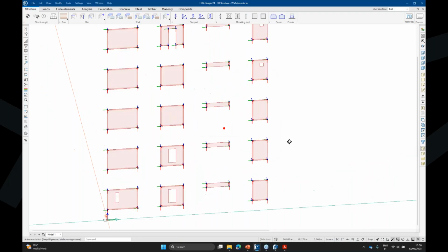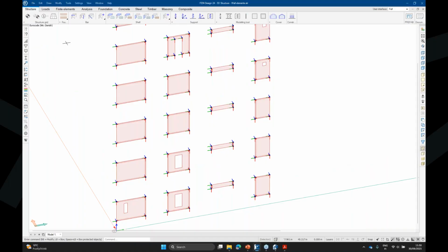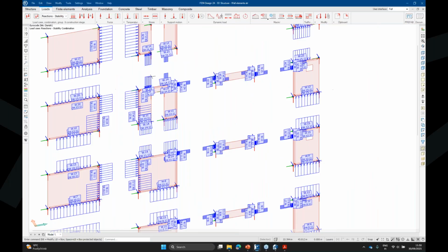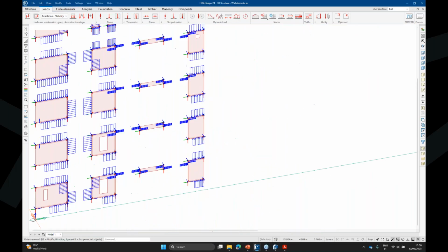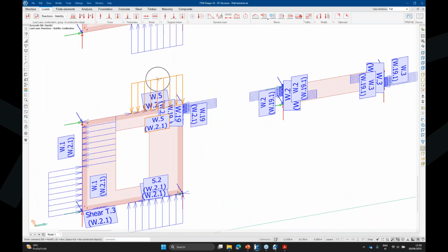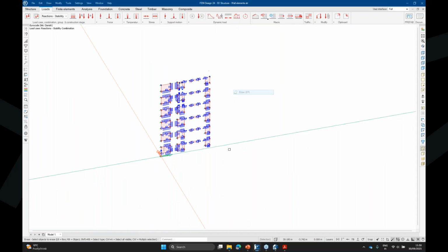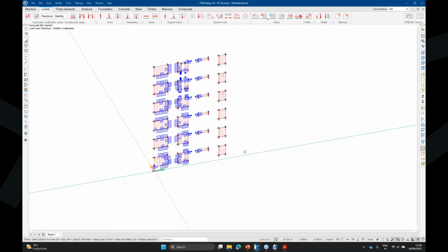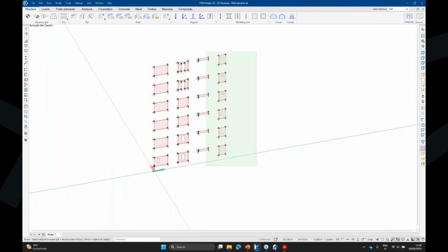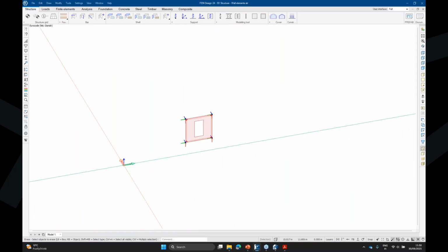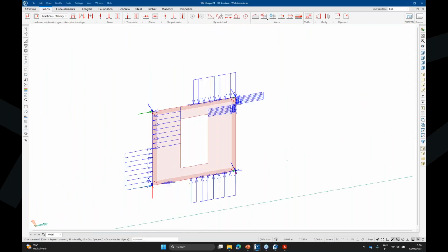So it will like export your whole model. So now all the essential information is in the new finite element model. Also the loading, that plastic loading, what we have been used after the optimization have been imported here. So now you can really use non-linear cracked model to calculate this one wall or all of these walls. If you are not that interested or want to just design one wall, you just simply delete all the others in this model, and now you just have one stable model which will have external loads.